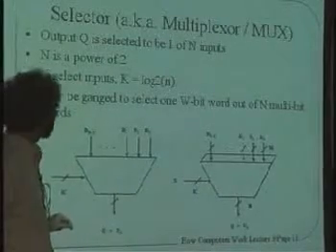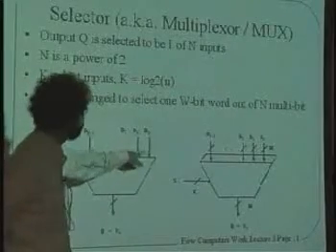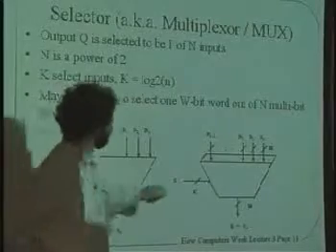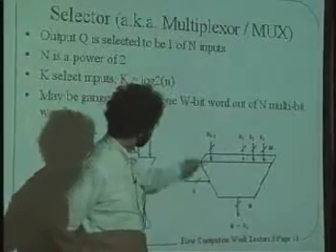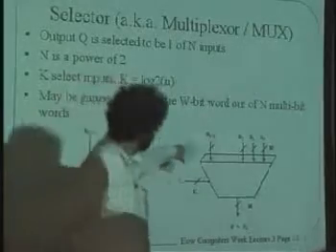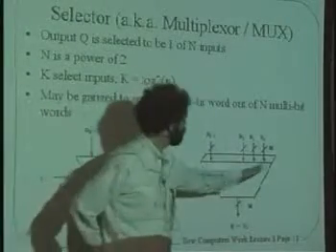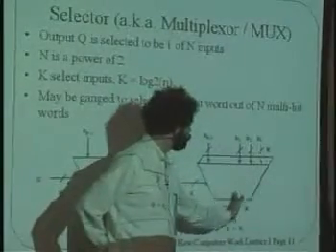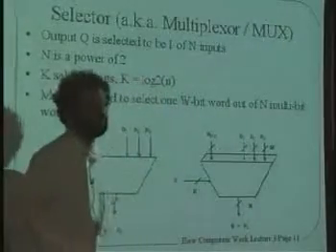Okay? Now, of course, this is shown here with only one bit going into each one of the inputs, but in fact you can have a wider number of bits, perhaps 32, and that's shown by the multiplexer being thick here. When you set a particular selection in here, all 32 bits will be chosen to pass out to here. And in general, this is the kind of selector that we're going to use.